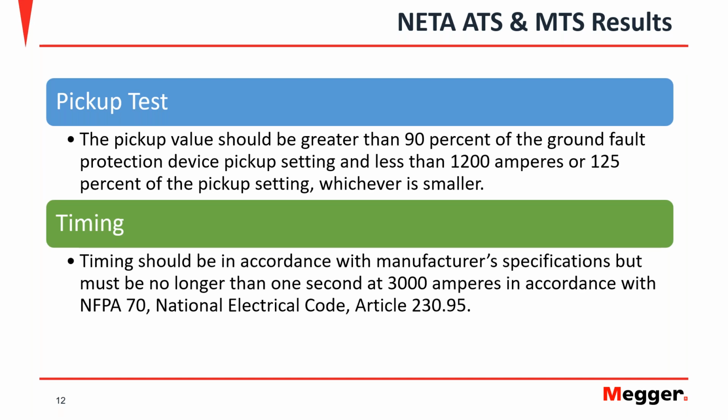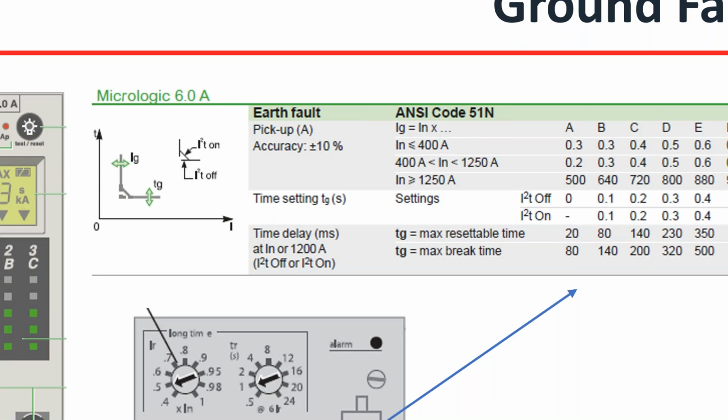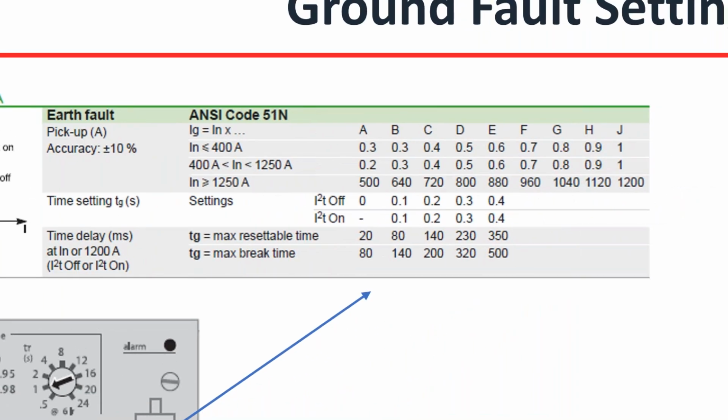And let me show you another part of my presentation here. This is again this table. I took it directly from an actual circuit breaker manual, the maintenance manual. And again, you see that for currents bigger than 1250, your dial stops being a multiplier and it actually becomes an actual value for current. So maximum is 1200. So for a 6300 amps breaker, the test current will be 1200.